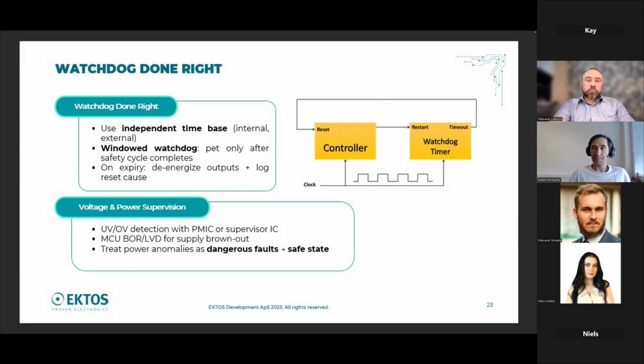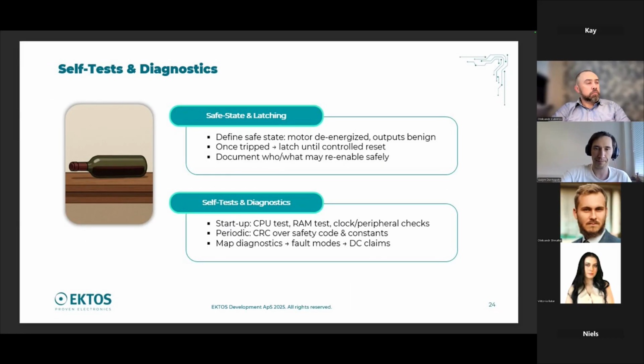And if you see overvoltage, it is quite a heavier fault, because it is difficult to control the consequences of this fault. You should consider whether you need a safety lock if this voltage is detected, just to de-energize the whole system or to transition to the safe state, to be quite guaranteed that even under overvoltage you can go to the safe state.